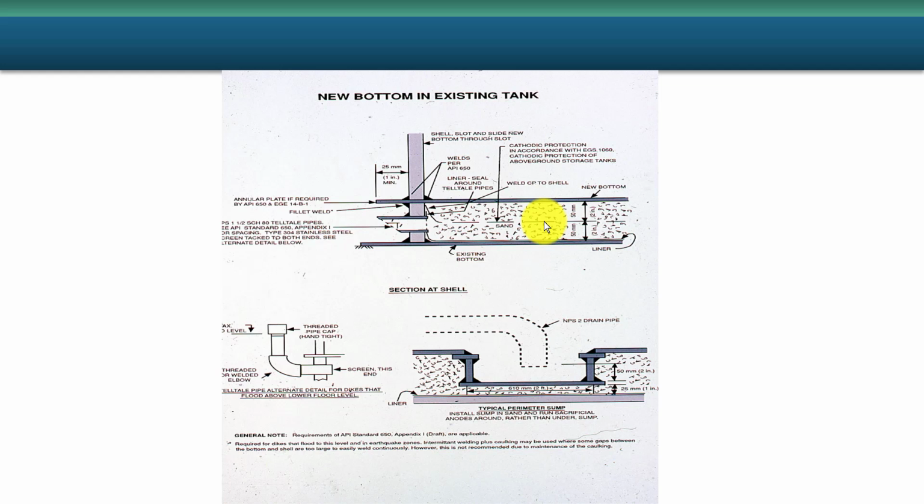That's a bad practice. The other thing is I recommend not seal welding this because it's almost impossible to do a good job welding it since it's in a bad position for welding. If the tank were to suffer uplift from seismic or overpressure or whatever, a crack in that lousy bottom weld could propagate into the tank bottom or shell and cause a catastrophic release.